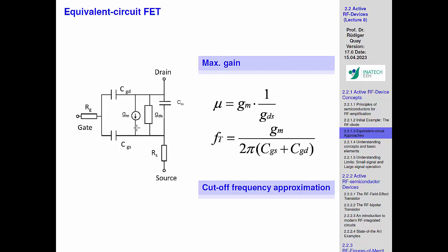And this can be expressed when you, for example, now check a quantity which is a simple definition of the cutoff frequency of the current gain. Yeah? So obviously it's good if this transconductance, the forward, is high, then you get a forward component into the story, which helps you to get the current gain cutoff up. If the capacitances are high, then we are in trouble because then this will delay us.